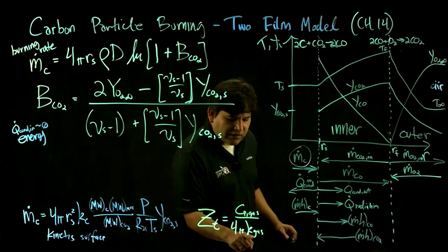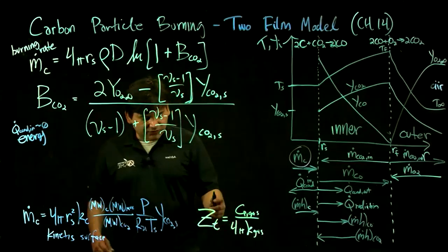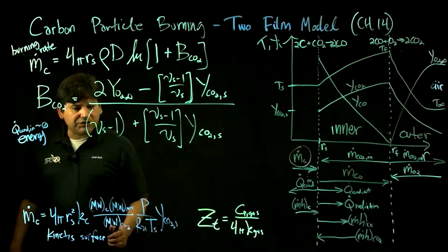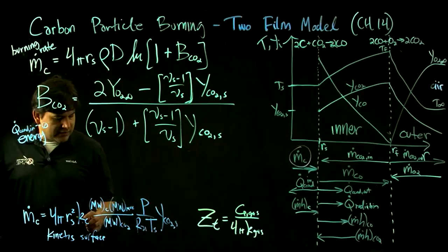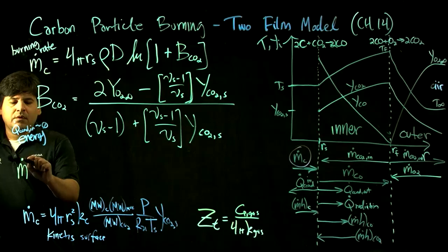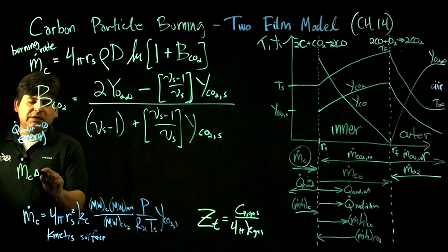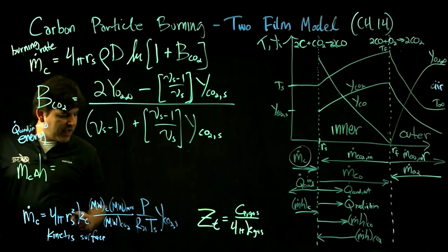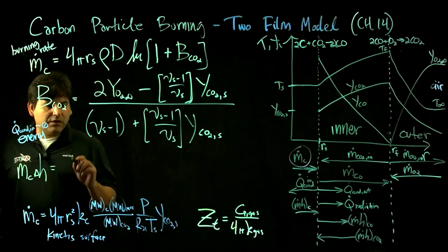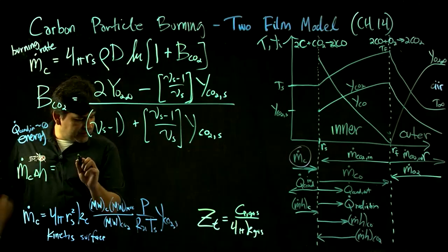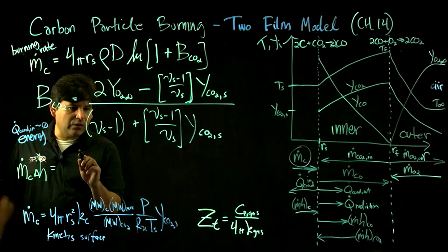This is the thermal conductivity of the gas. So defining that, we can get this big expression here, that the burning rate of the fuel times the enthalpy of combustion all has to balance all these other effects here that I'm about to draw out.